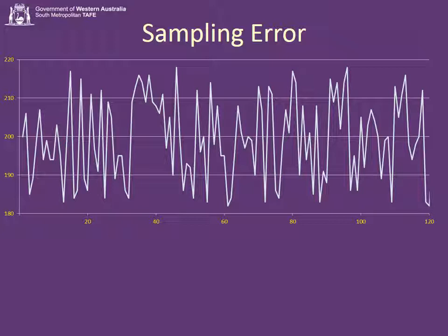You should try and mount the sensor as far away from the fan as you possibly can, but without getting near to any bends or curves or anything else in the ducting. It's often very difficult to find a good location, and more often than not we have very, very unstable signals like this. We can't control to a signal like that.